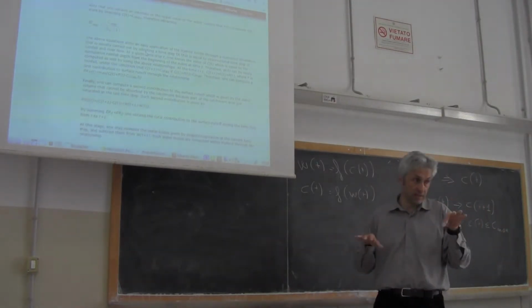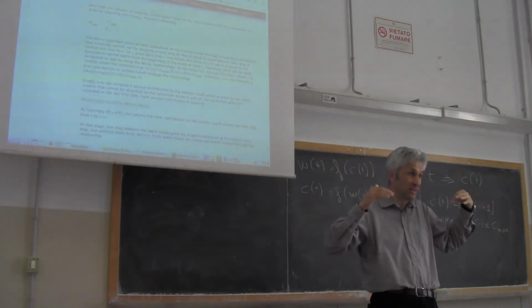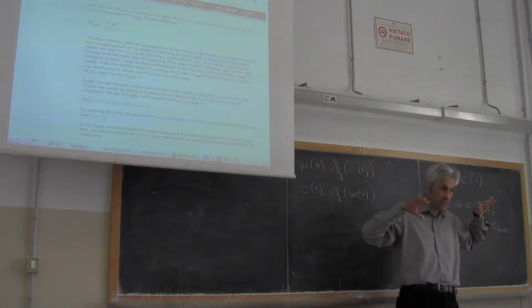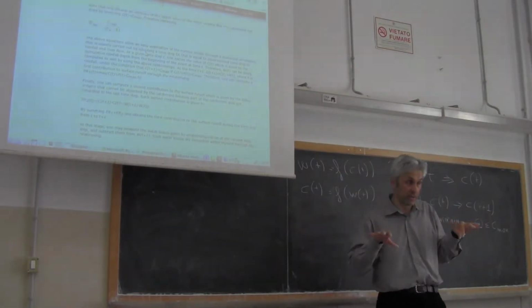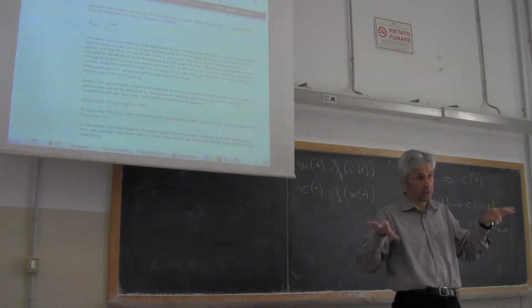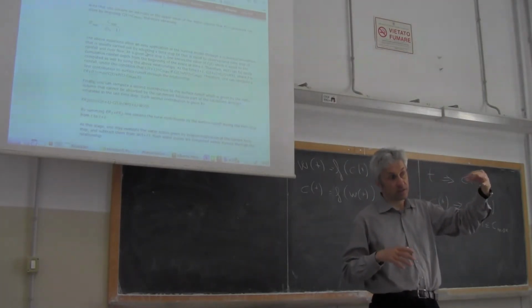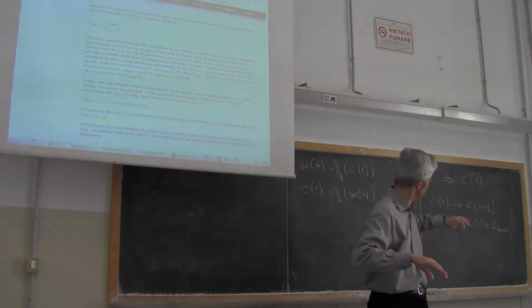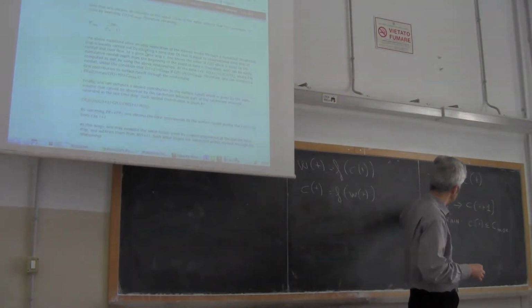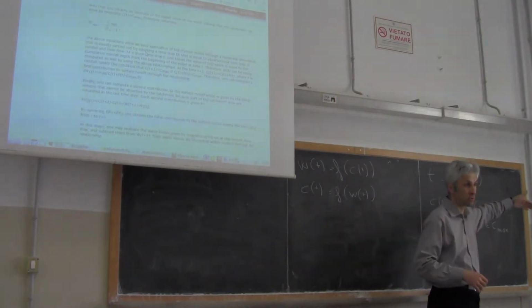The catchment gets saturated, and whatever rains above Cmax doesn't infiltrate and is not stored. It is immediately transformed into surface runoff, which means, in the end, river flow. So I have my rainfall data that allow me to compute the progress of Ct, from Ct to Ct plus 1, Ct plus 2, etc.